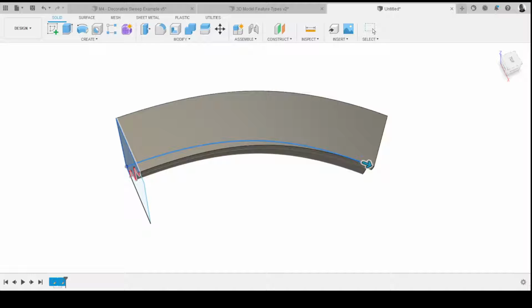No, I would say if you go back and just edit your path sketch, edit that one. So if you zoom in, yeah, you would have thought that would have been okay. It doesn't look too bad. No, it doesn't look too bad. But you can just try adjusting your path and seeing if you make it sort of straight coming up here. So if you click on that, yeah, try that. And it might be that it's too tight, as it's trying to actually bend that shape around that path. If it's going to self-intersect and make a shape which actually couldn't be created, it's not going to compute it because it would be, you know, incorrect, if that makes sense.